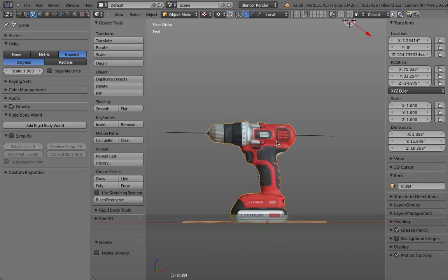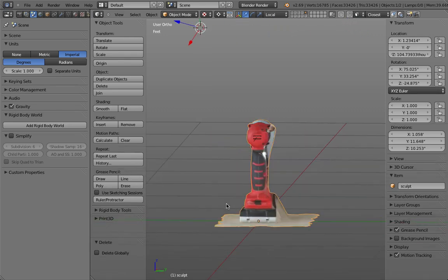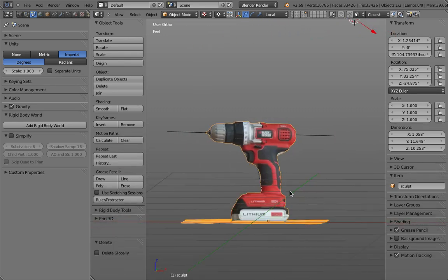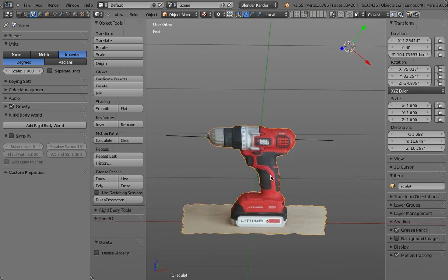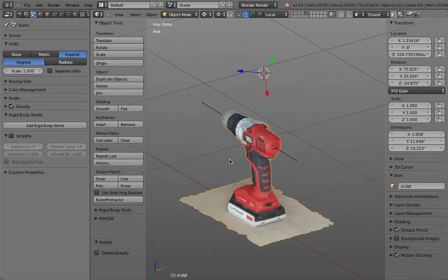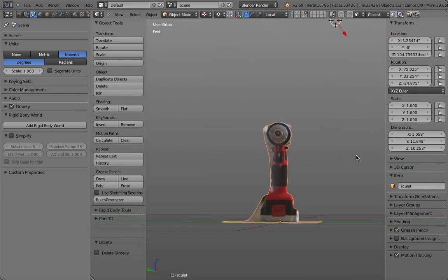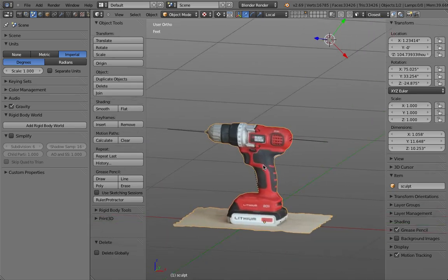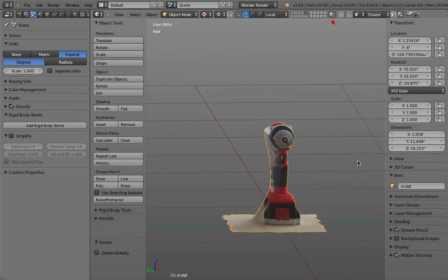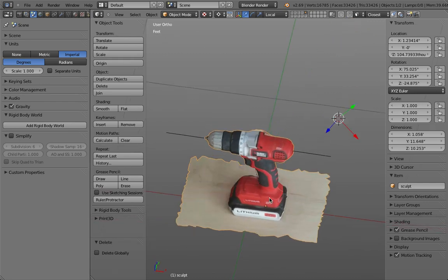So think about, for example, foam modeling. The top part, I would use a block of foam, put it on a wood turn, and just wood turn this profile, and then end up basically with a nice cross section. The handle part, basically, I would take sandpaper and sand everything nice, soft, and round. And the battery pack, I basically could use nearly even the bandsaw and cut everything away, because very much those are linear cuts.